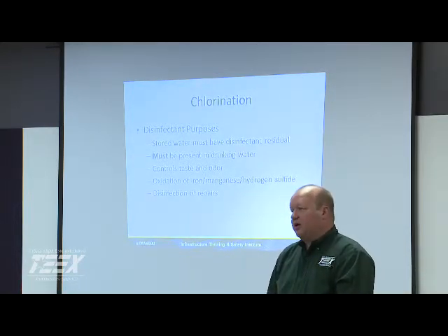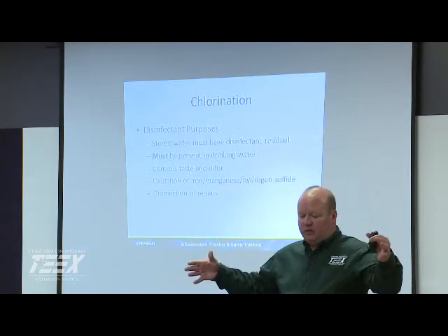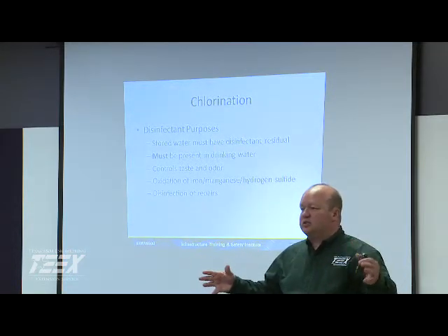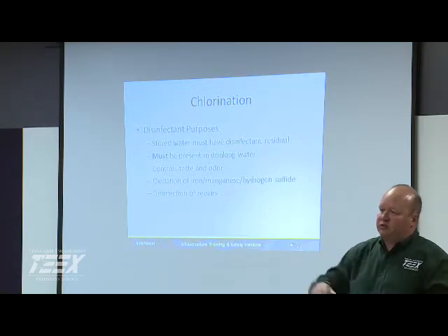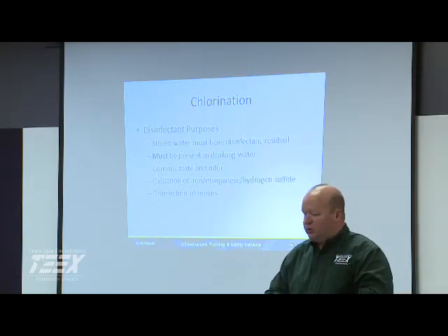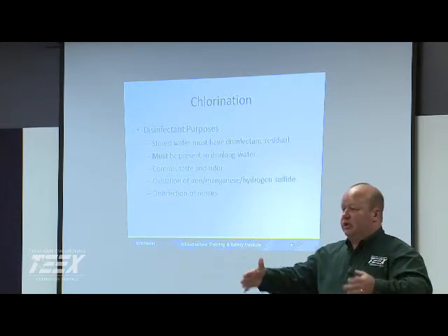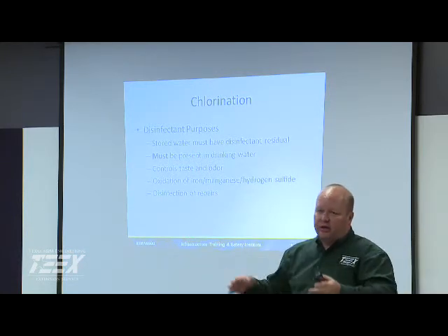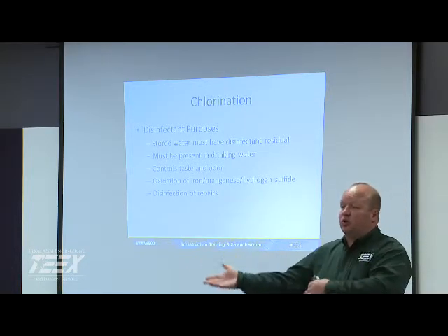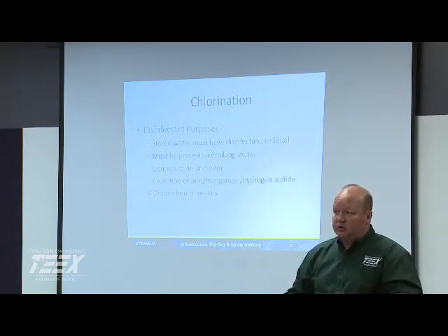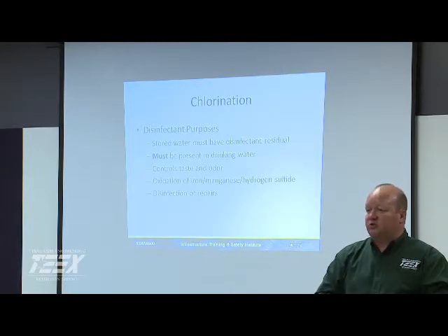Yeah, because we had a big issue when we were building that pipeline. They had a 60-inch pipeline, 30 miles long, going from San Antonio all the way down to the ASR facility. So what they did is they did slugs, and they would move that slug down and re-chlorinate it and all that. But then when you get to the end, they have to dechlorinate it. You can't just dump it on the ground. So those are things you have to consider.